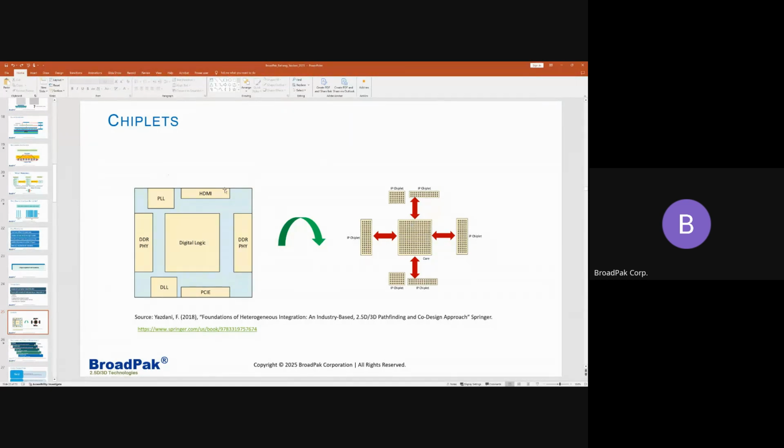And the advantage is that these interfaces become independent of the die, meaning they don't have to be at the same process node, so you can integrate it on the same SoC. So your core logic, where you do the compute, is going to be very important. It could be, let's say, at 3 nanometer nodes, whereas the DDR5 could be at 16 nanometer nodes, with the same bandwidth you connect it. And with this, you can lower the cost.